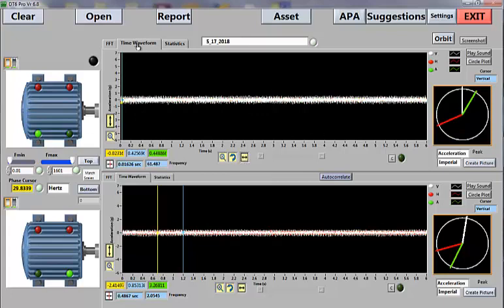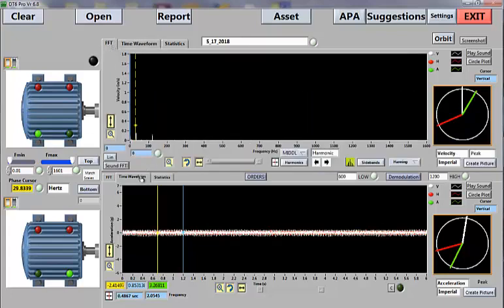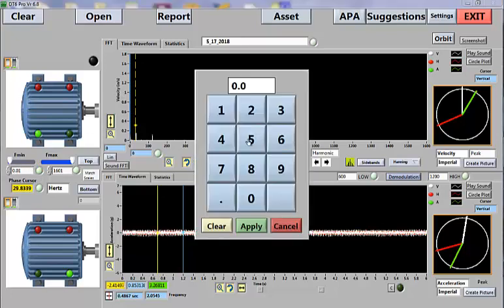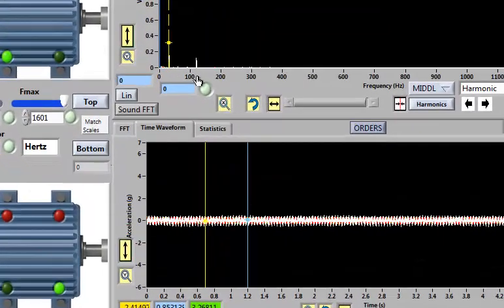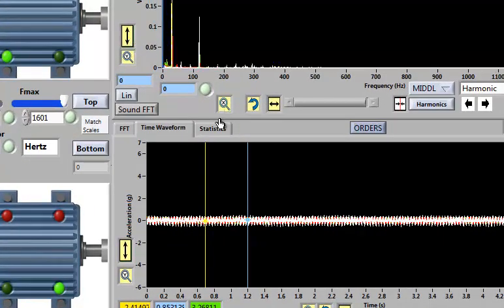So here, if I go back to the drive, again, I don't see anything super unusual in the time waveform, so I'll start taking a look at the FFT now. The FFT starts off in velocity, which makes sense. Most people use velocity. Usually the first step I'll do is I'll set my F min somewhere around 5 hertz or so, or 300 RPM, whether you use hertz or RPM. Usually doesn't mean anything major. I just like hertz. I'm a little bit more used to it, but you could switch that right here if you wanted.